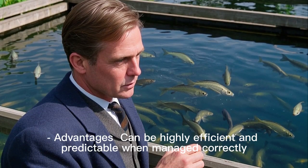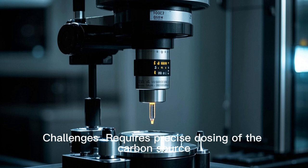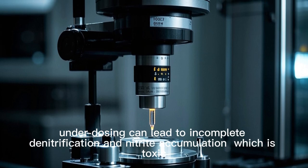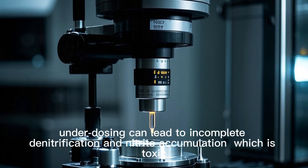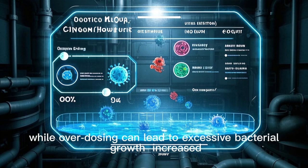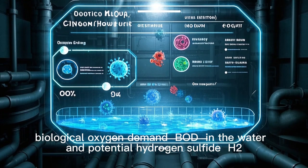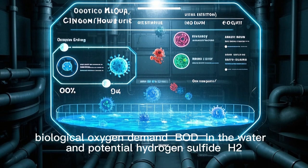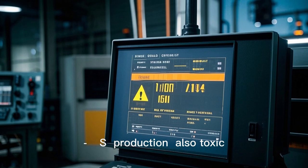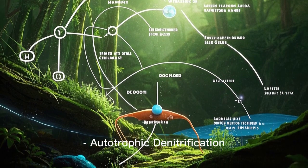Sulfur-based autotrophic denitrification, SAD. While primarily autotrophic, some systems use sulfur as the electron donor. Advantages: can be highly efficient and predictable when managed correctly. Challenges: requires precise dosing of the carbon source. Underdosing can lead to incomplete denitrification and nitrite accumulation, which is toxic, while overdosing can lead to excessive bacterial growth, increased biological oxygen demand, BOD, in the water, and potential hydrogen sulfide, H2S, production, also toxic. Requires careful monitoring.